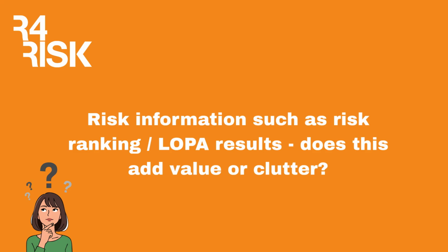It depends what outcomes you want at the end of the day. So if you want to go fully qualitative, it might not make sense to have all those numbers in there. But if you want to do a fully quantitative bow tie, then absolutely include those results. And there are a lot of programs now where you can get a nice bow tie picture, but have all that data as almost metadata and hidden, so it doesn't actually clutter the picture for the people who need to use it.